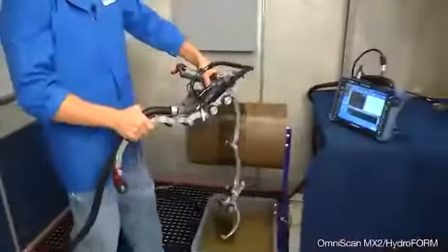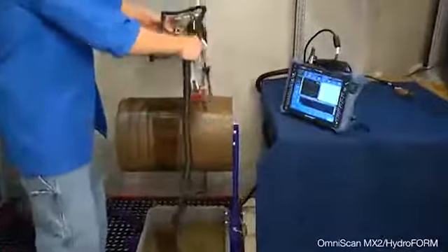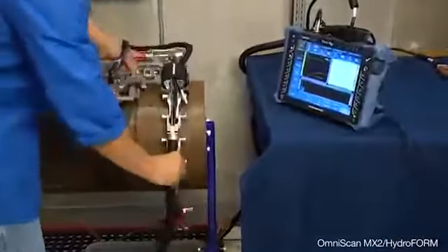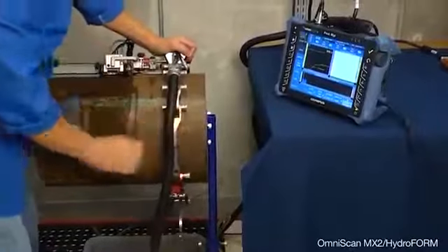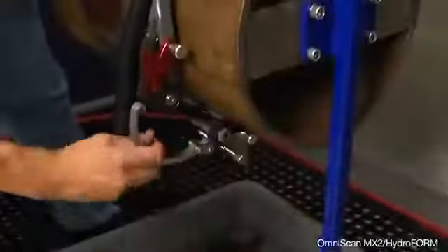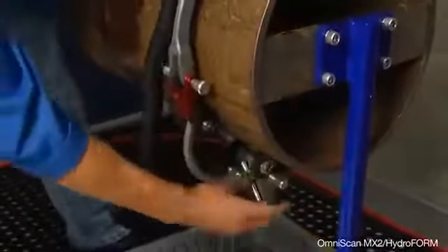Grab the chain scanner with 2 hands, and place it around the circumference of the pipe, keeping it as parallel as possible to the pipe surface. Reach around with 1 hand and grab the hook and set it and clasp it tight.